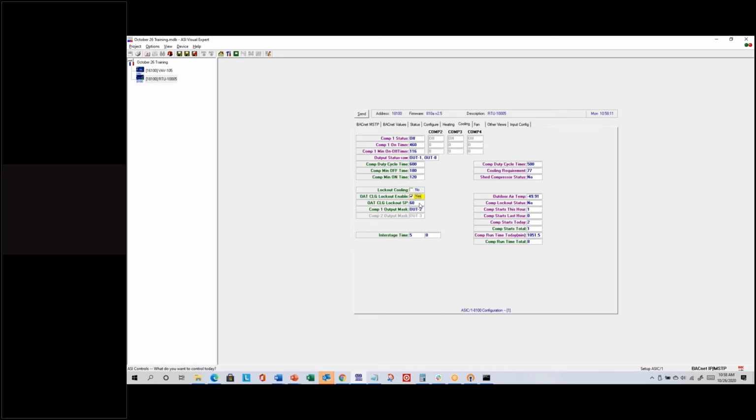And the outside air temperature can get to the controller in a couple of different ways. The simplest way is to wire an outside air sensor directly to input number 5, which is reserved for the outside air sensor. That's not really that practical when you have multiple controllers. You don't want to take the time and expense to wire a different sensor to each controller, because the outside air is basically the same for all of them.